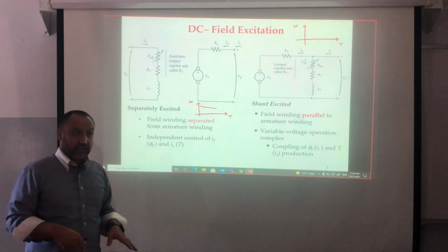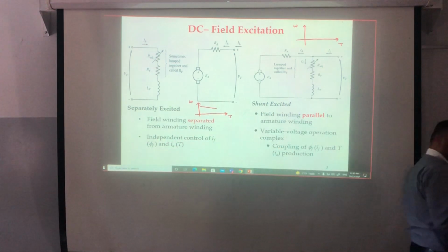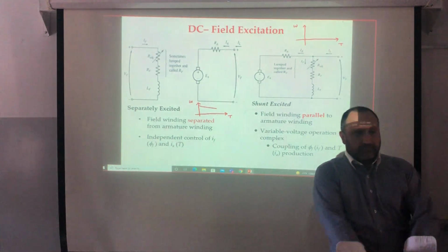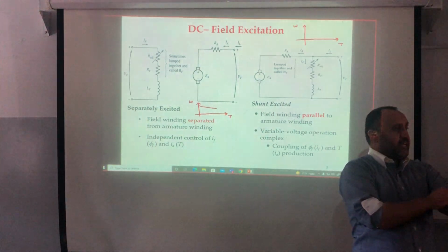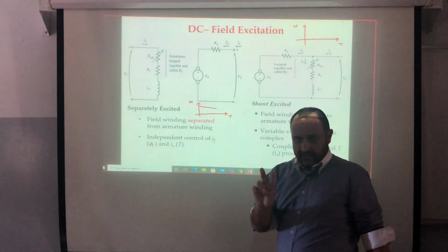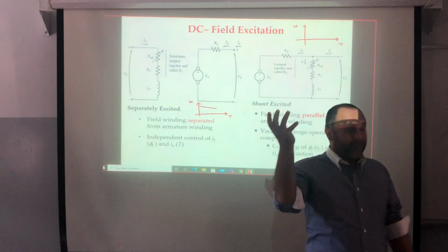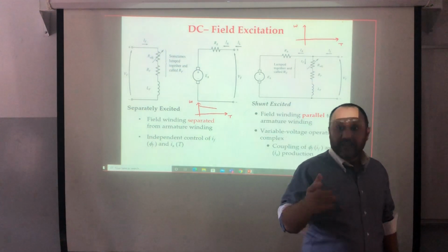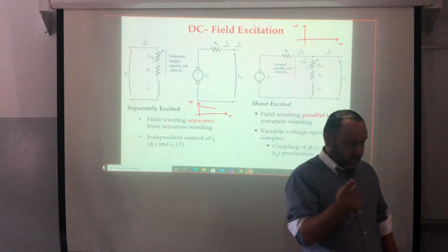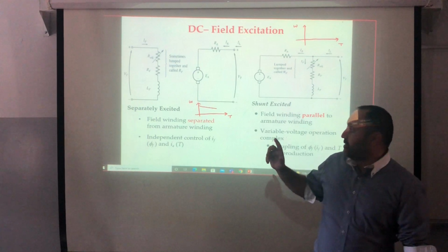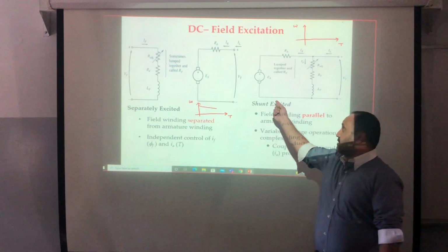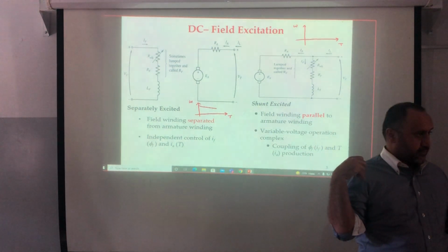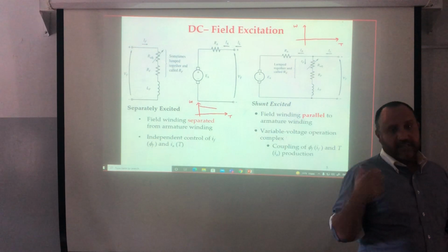What is the meaning of the armature reaction? Do you know this term, armature reaction? Simply, in the machine, you have two fluxes. One we call the field, the main flux. And the second one is caused by the current flowing inside the armature, correct? Now, simply, the armature reaction here is that the armature flux will weaken the main flux. E_b, this is the back EMF.